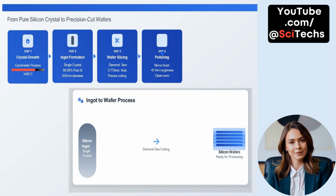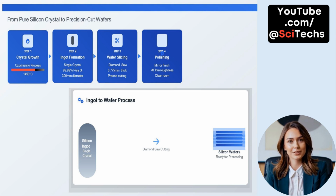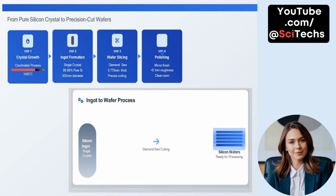The journey from raw silicon to a processed wafer begins with crystal growth. Using the Czochralski process, silicon is melted at around 1450 degrees Celsius, and a single seed crystal is dipped into the molten silicon to slowly pull out a large cylindrical crystal called an ingot. This crystal is highly pure, typically 99.99%, and has a uniform atomic structure. Ingot formation produces a monocrystalline rod, often with a diameter of 300 millimeters.